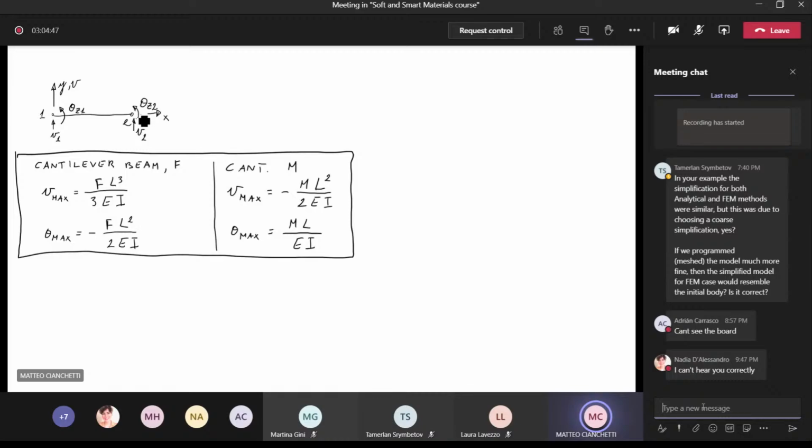So if we activate each single degree of freedom, setting it equal to 1 and all the other degrees of freedom to 0, the nodal vector of loads will describe each column of the element stiffness matrix. If we start with the first degree of freedom, it will give the first column. The second degree of freedom will give the second column, and so on and so forth.